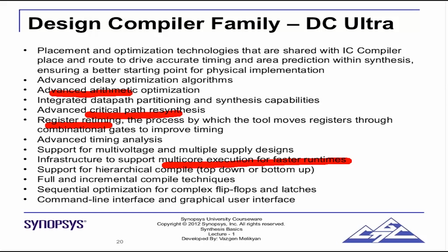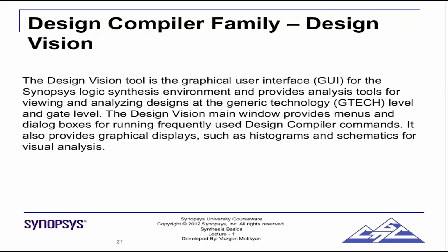But for the scope of this project, DC Expert should be sufficient, unless you are going for a very high speed design or something like that. DC Expert should be sufficient. And the graphical user interface for this is called Design Vision. Again, it's a separate feature, not a separate tool. It provides analysis, viewing and analyzing designs at the GTECH level. It provides menus, dialog boxes, drop down menus, and so on. But I would recommend starting with and sticking with the text-based interface, that is the command line interface.